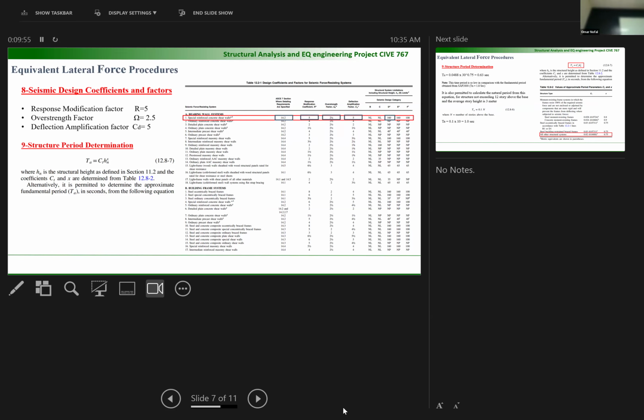something like this, right? So let's say we are gonna capture the delta of the building with the force on the building. The elastic design, if an earthquake hits the building with elastic design, we need to have a linear relationship, like as the force increases, delta is gonna increase. It's gonna be something like this. Let's make the line. We're gonna have, for example, something like this, okay? So once an earthquake hits with a specific force and the earthquake is gone, this building is gonna return to its original position. There is no inelastic deformation, okay?